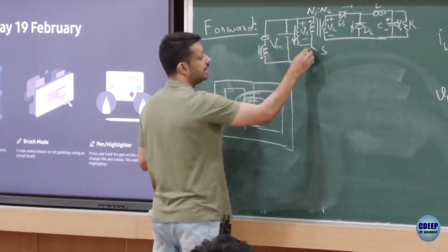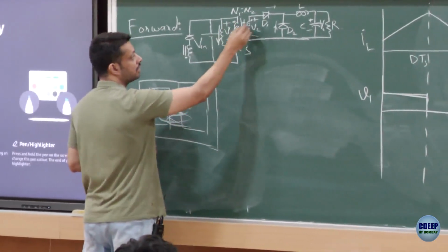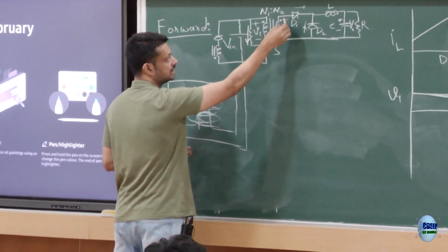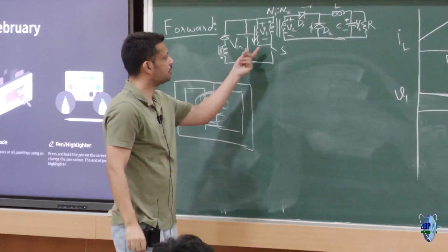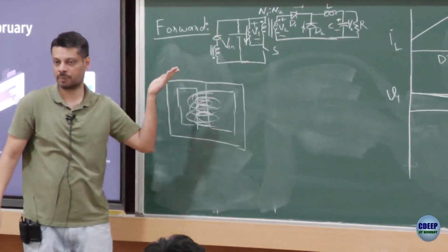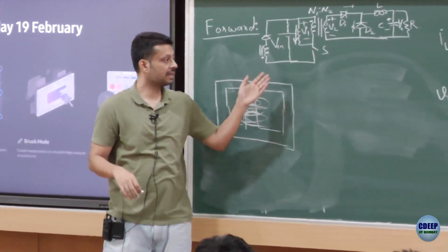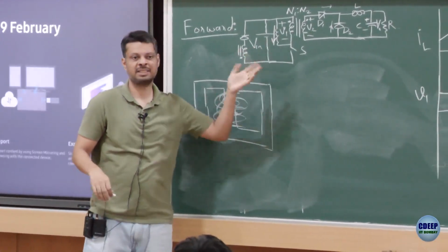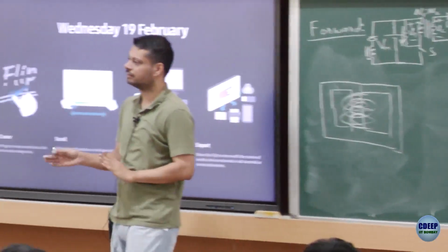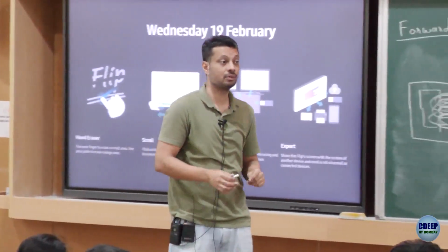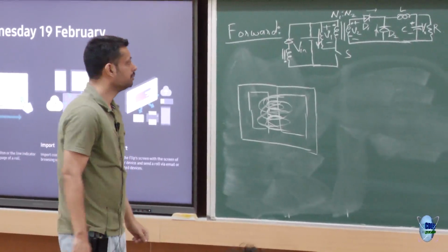If it cannot flow through the switch, if it leaves the dot, it cannot enter the dot from here because there is a diode also. So that is also one way you see this circuit cannot really operate with a practical transformer. One way or the other, these are all interlinked because the flux and the LM are interlinked. So they are interlinking arguments, but you can see whichever angle you think is more convincing to you.